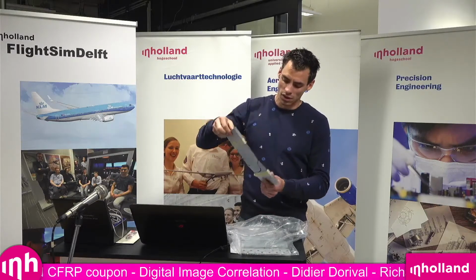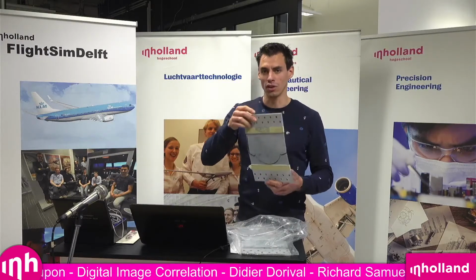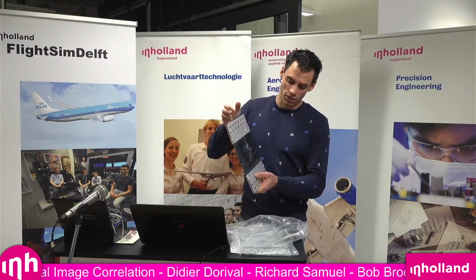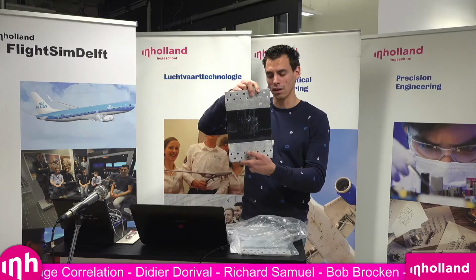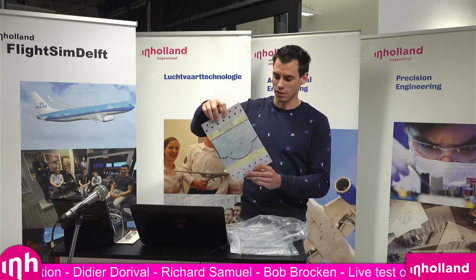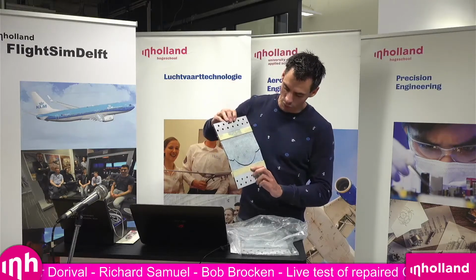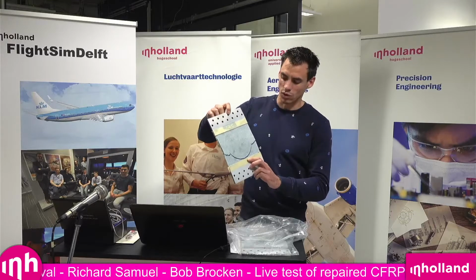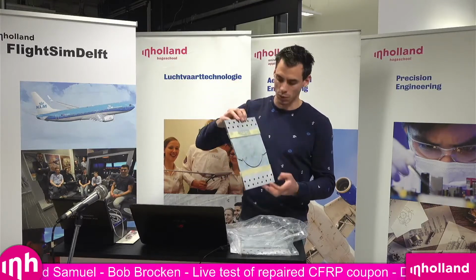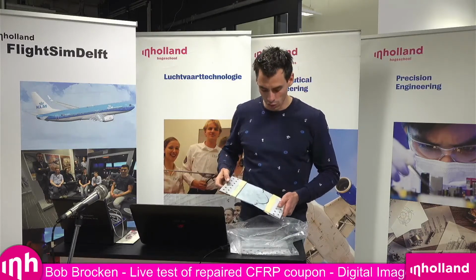However, because you remove such a large section of the load-bearing material, which is the 0 degrees, and you have still that ply remaining on the background, you get some sort of an unsymmetrical laminate, and this results in bending during the testing, and then a peel off of the repair patch. And as soon as the repair patch lets go, it's only held by those edges of the sample, and therefore it breaks at a relatively low force.